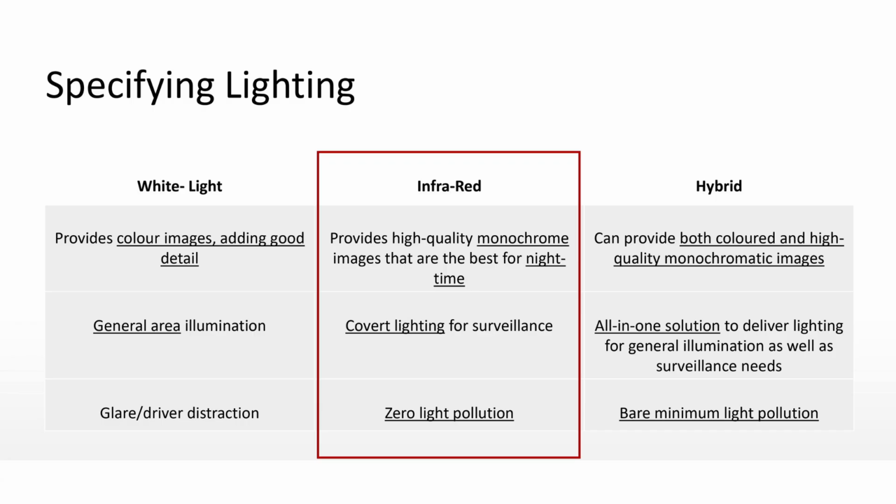Now, interestingly, while they're the three main options, we have been doing a little bit of testing with others as well, which I think we're at the point where we're happy to start talking about. One of which is 810 nanometers. Now, the reason for going with that in-between wavelength is we perceive that it's not as visible as 730 nanometers, so potentially better for use on motorway type applications, but it still gives you some of the performance for seeing through windscreens that 730 nanometers is able to provide.